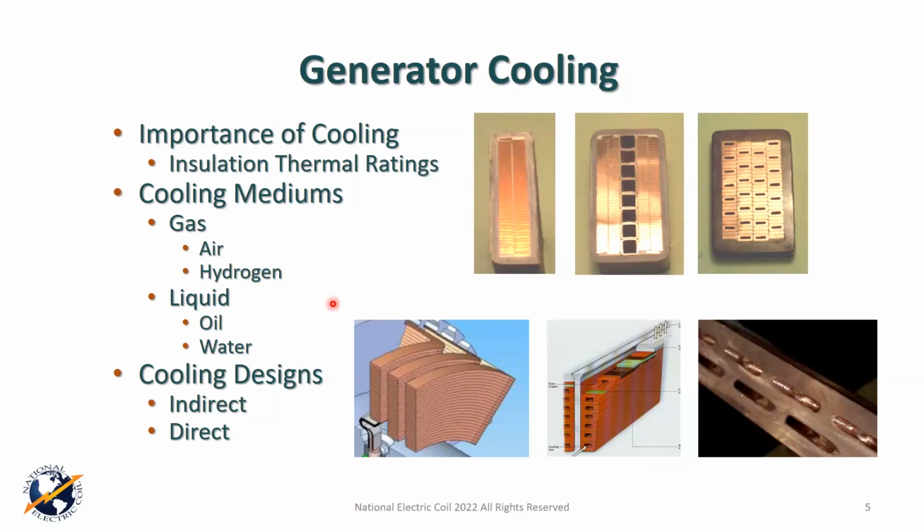The other direct cooled, we talk about liquids, and we have oil in here, but there are very few oil machines left. A lot of the oil machines were very early vintage liquid cooled machines. There still are some, and the oil is nothing more than pretty much transformer oil, what some people used to call mineral oil or 10C oil. And most of those have been changed out, but as I said, I know of at least a couple that are still running. Most prevalent today are water cooled machines, and oil or water, they're pretty much the same.